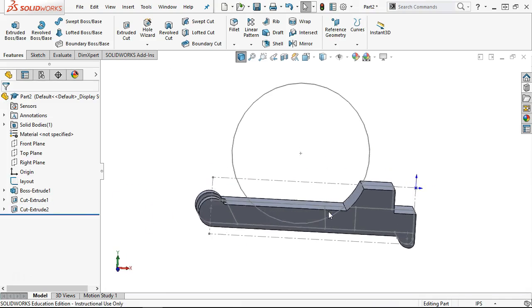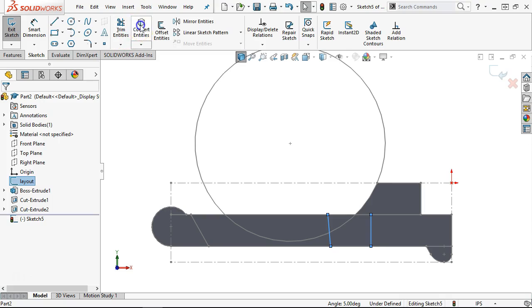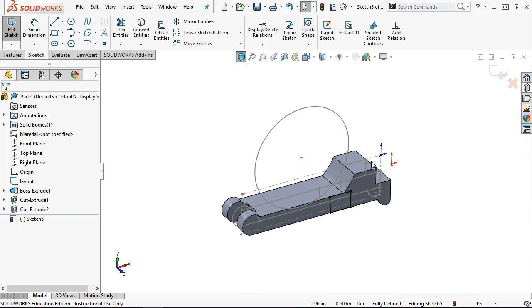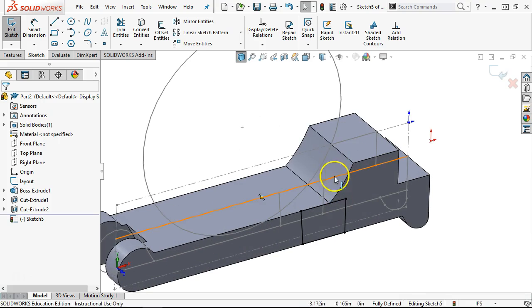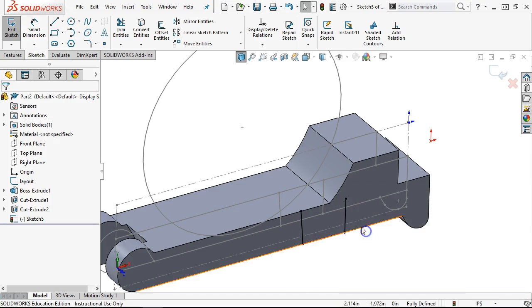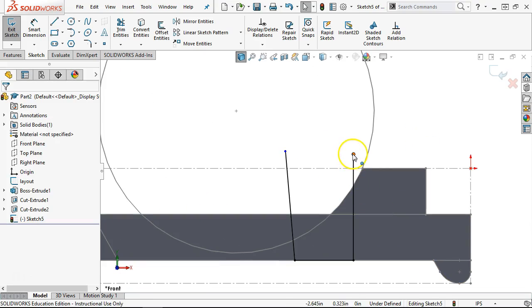So looking pretty good. Open up the sketch on the outside. Convert the entities. I won't worry about converting the top and the bottom. We'll just sketch those in. And then the depth. Didn't go far enough. We're into that geometry, and it does look a little foreshortened. So let's see, did I draw that one last? Nope. So let's put the one back in. And then again, because I did convert entities, I can pull that up and pull that one up. And we'll go back to Control 1.